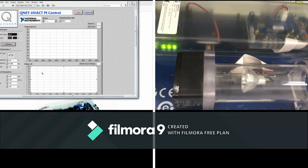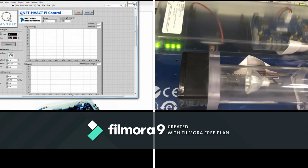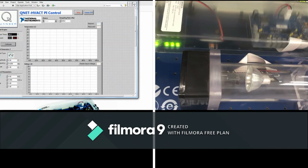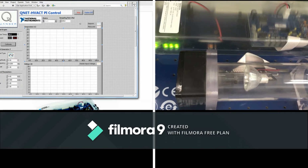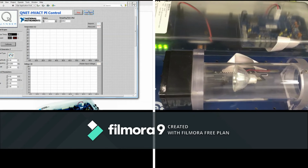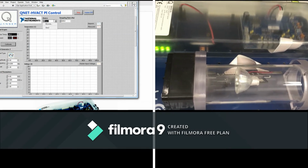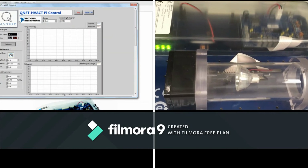We have our signal for voltage, our temperature scope, which has set point and measure point. We have digital scopes, and we control the signal through this signal generator element, and also the control parameters KP and KI, because we have a PI controller. We can stop the system from here, we can run from this button, and we can turn the heater on and off from this button. This is to select our device. This computer is attached to device number 2, and we run the experiment.